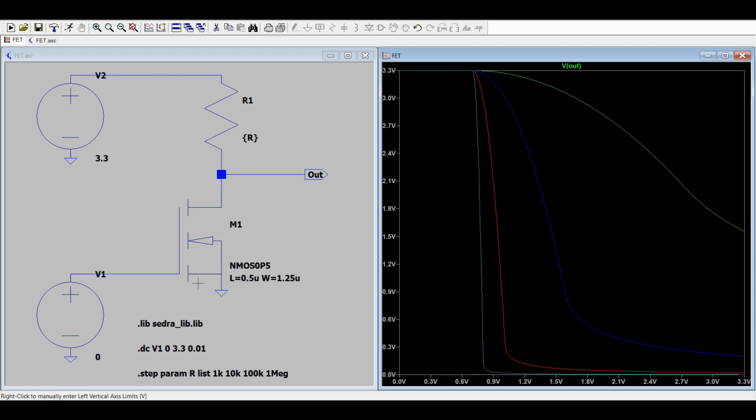And that's why we see for our green curve here that we're actually at this level here. Now, maybe for this FET, the channel can have a lesser resistance if we increase the input voltage even further, but I'm choosing to drive this with 3.3 volts. It's just for us to get an understanding of how FETs work. If our resistor up here is larger, say 1 megohm, then 1 megohm is so much bigger than 1 kiloohm that our output is going to be very close to 0.